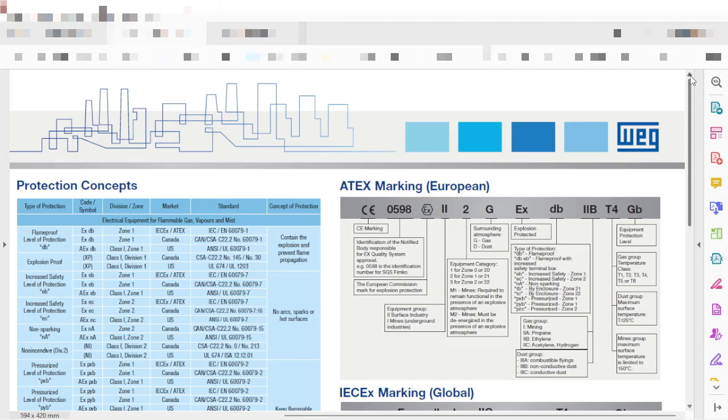The chemical process engineer in plant design not necessarily will be responsible for the development of the hazard area classification map, but in any way, the chemical process engineer will need to support the professional responsible for this activity. That can be the electrical engineer or most often the process safety engineer. The chemical process engineer will inform the other disciplines or the person responsible for the hazard area classification where the source of flammable gases is and also what the characteristics of these flammable gases are.